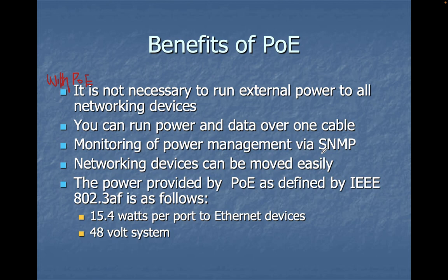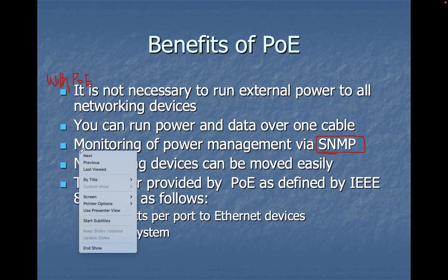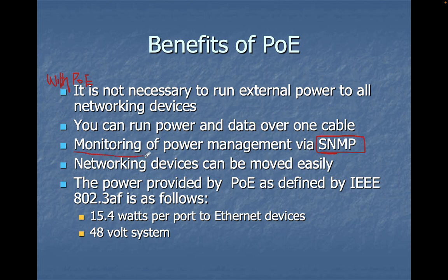With PoE, you can monitor what power you have on the system and what power you are sending to the PDs, the powered devices, through your PSE, the power sourcing equipment. We use SNMP, the Simple Network Management Protocol, to see what power we have on the system and how much power has been sent.